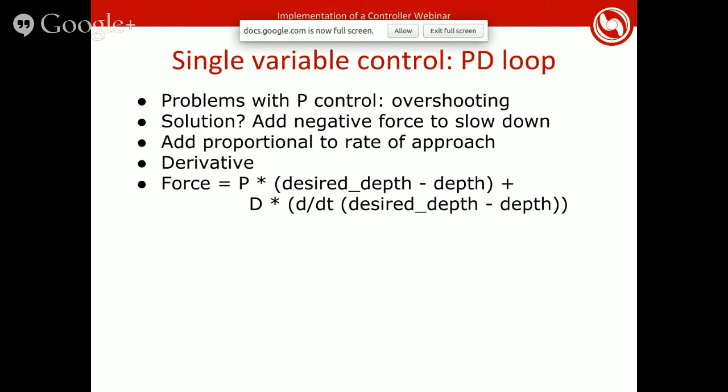It should be aggressive, so you should have a high enough P. And it should also not overshoot once it reaches the set point, so a high enough D as well. If you make D too high, that term might dominate the equation, especially if your signal is very noisy, because obviously the derivative isn't something you get for free. Usually the simplest thing you can do is take the difference between 2 points and divide by the time between them. And if you have a noisy signal, that can be artificially high. A high D leads to a noisy signal, that leads to more oscillations, which leads to more high D, and you'll know it's become unstable if you make D too high.